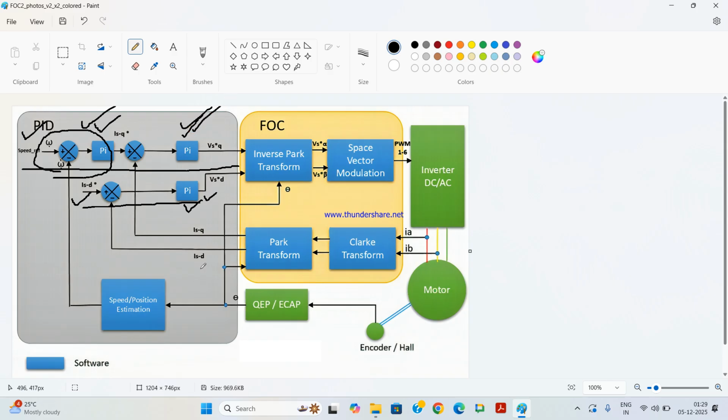Now you can think, if you conceptualize the Bode plot or the Nyquist plot, the three systems are coupled together with different natural frequencies, and they are dancing within different phase planes. How difficult it is. So exactly, the dynamic performance of the machine depends on the perfect tuning of these three PI regulators.